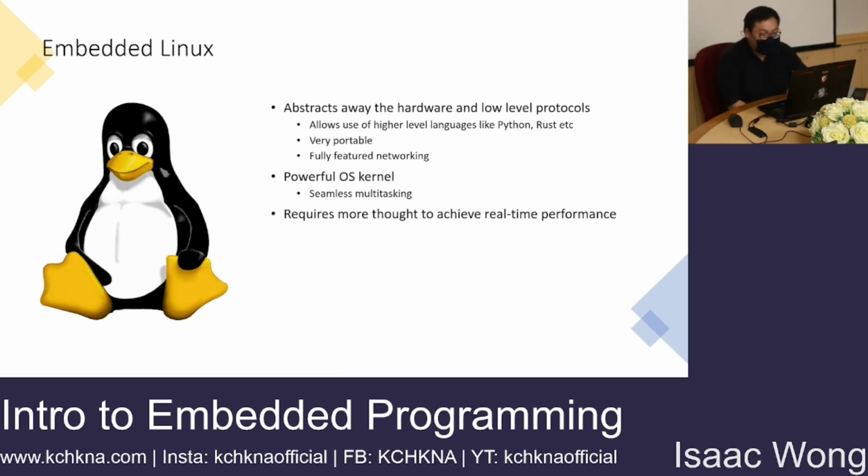Okay, so this one is not really an advantage, it's more a disadvantage, because embedded Linux has a very large and bulky kernel. It's very difficult to achieve real-time performance, especially when you use very high-level languages like Python. So it actually requires a lot more thought in the programming. And usually you have to use very low-level languages to actually achieve real-time performance on Linux.